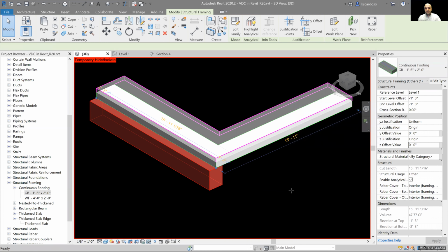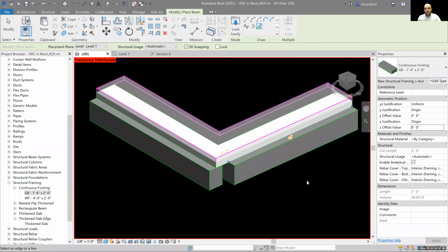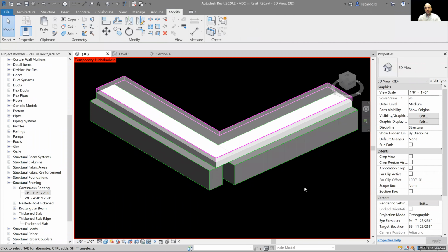So that's my biggest suggestion to Revit for you guys as users, to save you time, but also to eliminate headaches, is if you're going to use 3D snapping, commit all the way through, because then you can use your trims the way you want. You don't accidentally select a thickening and a grade beam and have them react, because Revit sees them as being completely different locations.